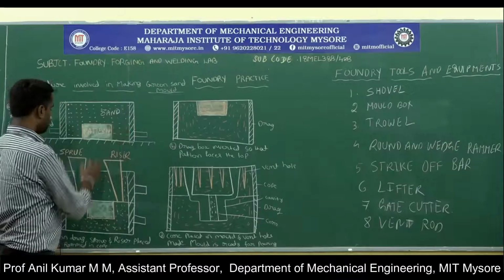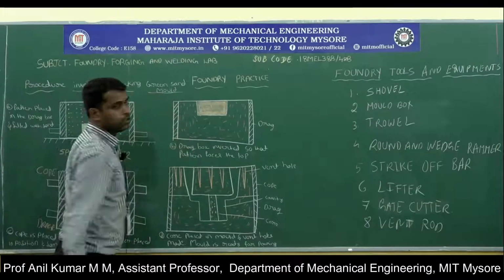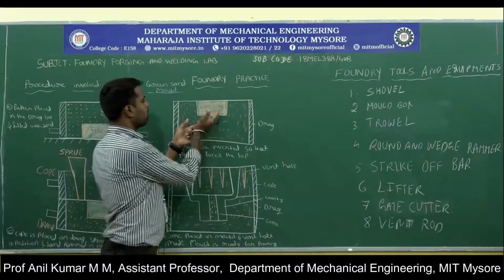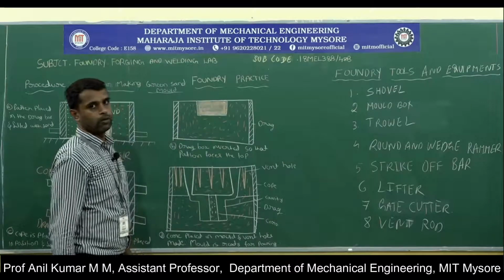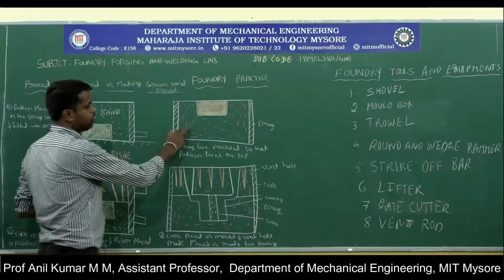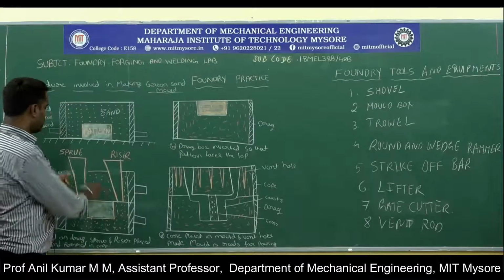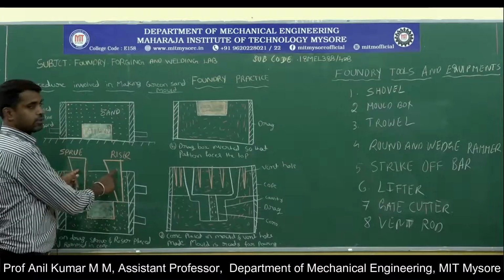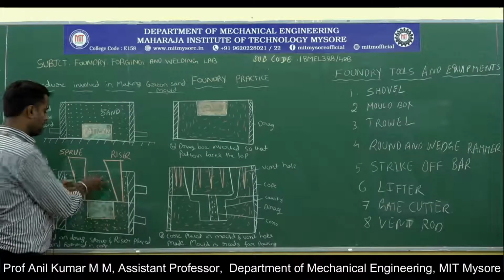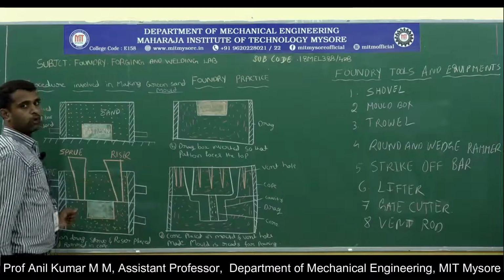Okay, after that, you have to invert the drag box. At that time, the pattern will face the top. After that, place the cope box over the drag box, and then place the sprue and the riser in the appropriate location, and then again fill the sand in the cope box.